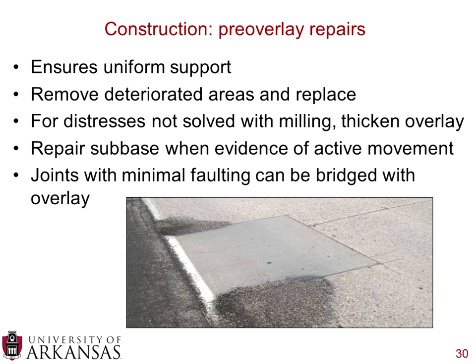The next thing you want to do is any sort of pre-overlay repairs. This ensures your uniform support. So if you do have deteriorated areas, you would want to remove those deteriorated areas and replace them. And don't worry, David, I have a note here to get back to you on the ASR in particular.